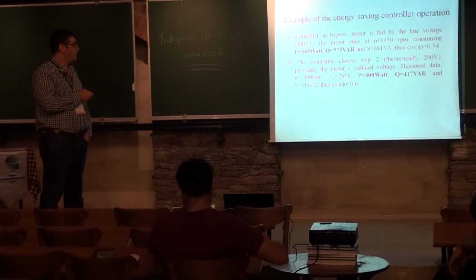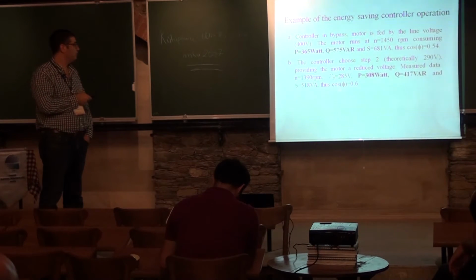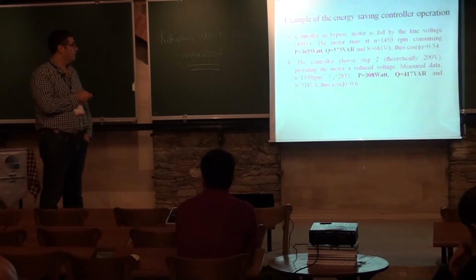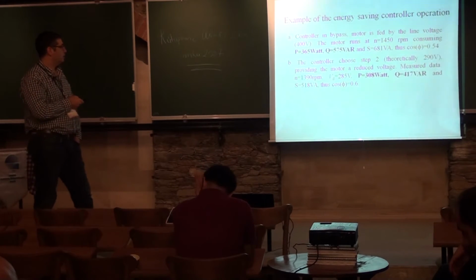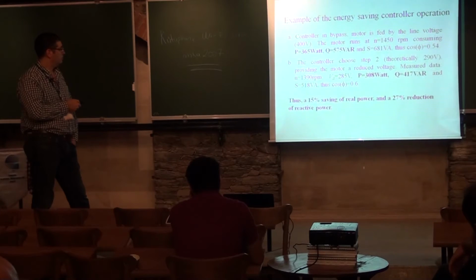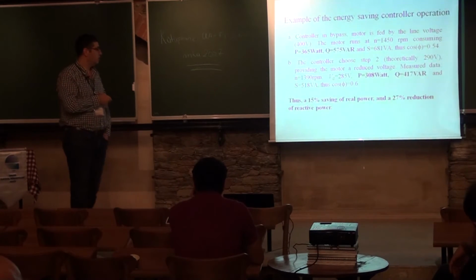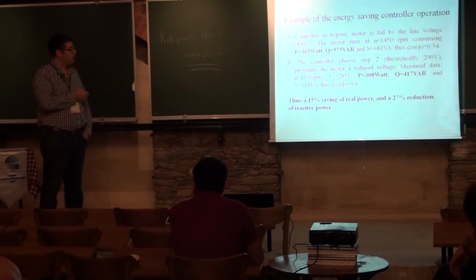So by itself, it went to this value of the voltage, reduced the voltage to this point. Power factor was somewhat improved. Reactive power is reduced, and even active power is reduced. So about 50% saving of active power and 27% reduction of reactive power.